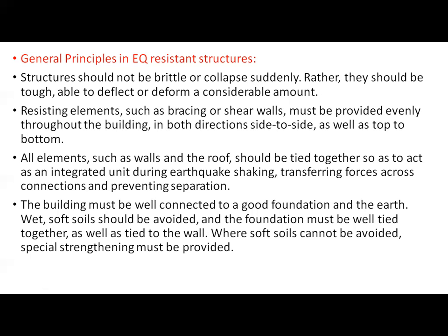So for that purpose, we have to take care of the binding of each and every component, concrete and steel. Next, they should be tough, able to deflect or deform a considerable amount. That means whatever materials we use should be ductile. That is the first point. And the second point is that deformation should be in a considerable amount.